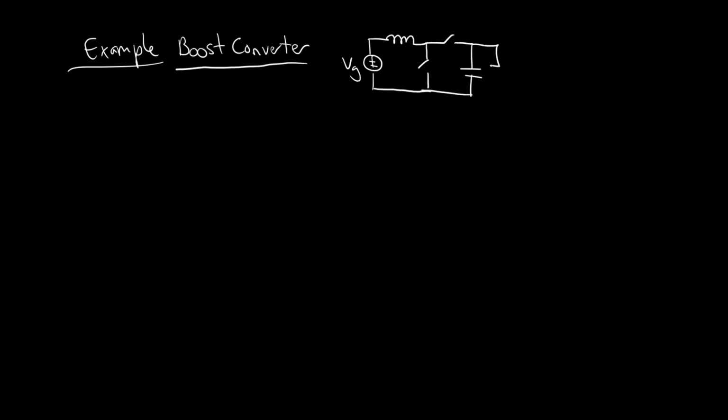So this is a simpler converter, right? There's one inductor, so one capacitor. We have our load resistance. Again, we're modeling our loads as resistors. This is our output voltage. We have Q1 and Q2. Cool. Very simple device. So this is what we're going to be analyzing.